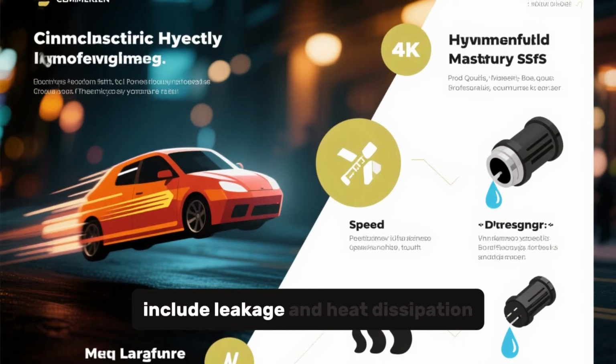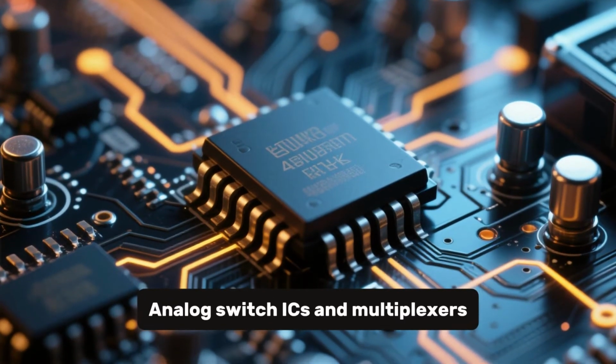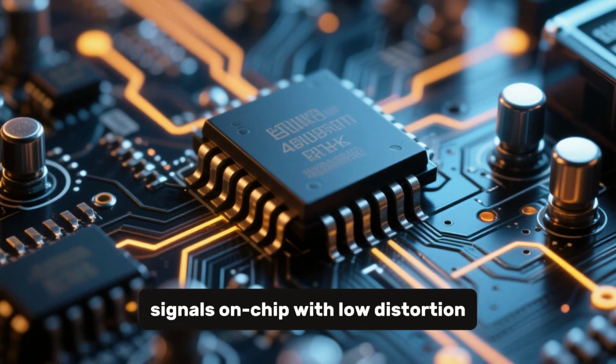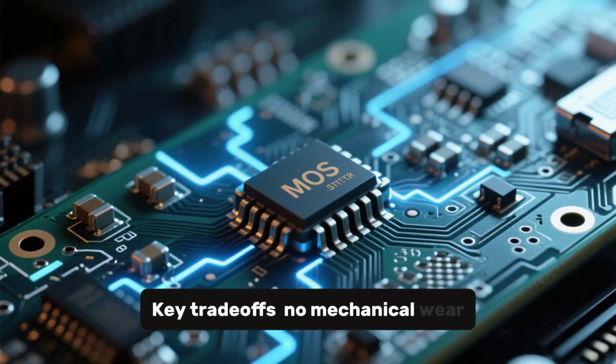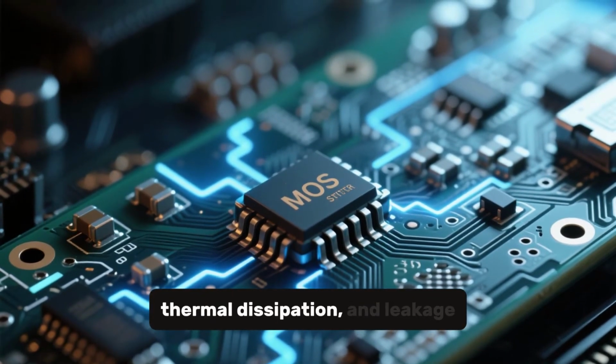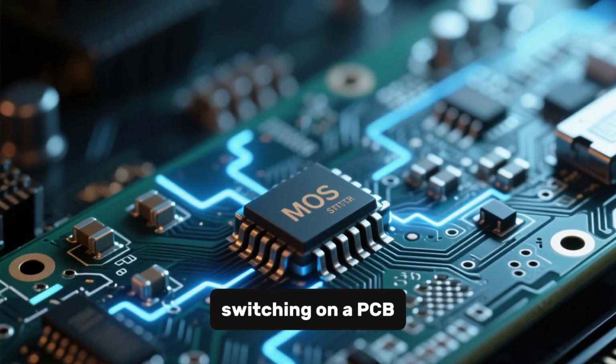Disadvantages include leakage and heat dissipation. Analog switch ICs and multiplexers route analog and digital signals on chip with low distortion. Key trade-offs: no mechanical wear and high speed versus on-state resistance, thermal dissipation, and leakage. Visual: animated MOSFET switching on a PCB.